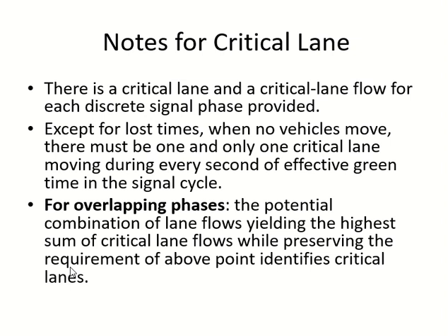Whenever you have effective green, so what is effective green? You have the total time minus the lost time. In the total effective green time, at least one critical lane should be open, because every phase is for a critical lane, right? When one phase closes, the other one should open. So one critical lane closes, the other one should open. Clear? And then there are lost times as well, where this may not happen. But in the remaining time, at least one critical lane should always be open.